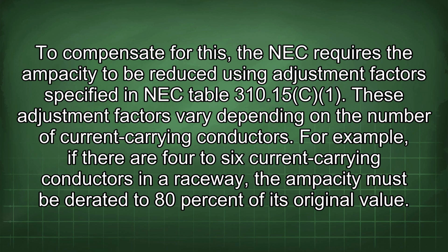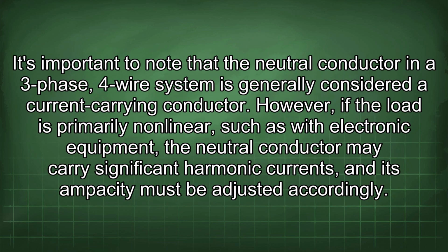of its original value. It's important to note that the neutral conductor in a 3-phase, 4-wire system is generally considered a current-carrying conductor. However, if the load is primarily nonlinear, such as with electronic equipment, the neutral conductor may carry significant harmonic currents, and its ampacity must be adjusted accordingly.